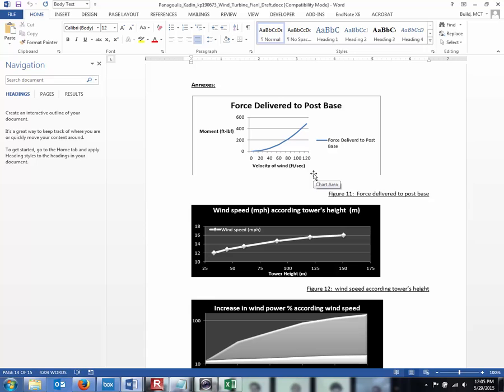Well, that's another good question. So any rotating machinery is going to have a stall torque, some torque which it has to overcome. So a little tiny gust of wind probably wouldn't get the thing spinning. Once it's up to speed, yeah, there's a max speed after which, and I'm trying to remember the name of it, but that's the max RPM, if you will, where there's not enough extra wind coming in to make it spin any faster.